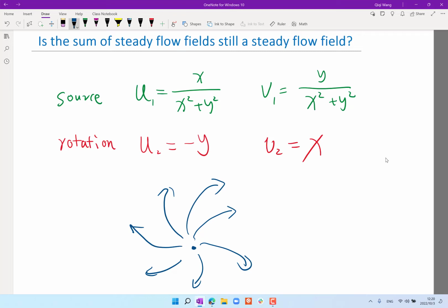If you integrate the pressure gradient over a circular path, the total integral of the pressure gradient along that contour direction has to be equal to 0, right? Because you are integrating the gradient of a scalar along the circular path. So that means the pressure cannot torque the flow, and yet as the flow expands outwards, it is gaining more angular momentum. That means this cannot happen in the real world.